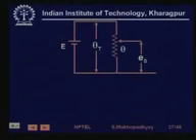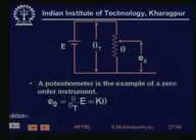Since the position is actually a mechanical variable, there is not going to be too fast a movement. The electrical behavior is so fast compared to that, you can just assume it to be a pure resistance, and then you have what is known as a zero order characteristic.